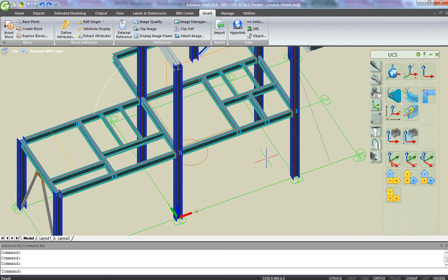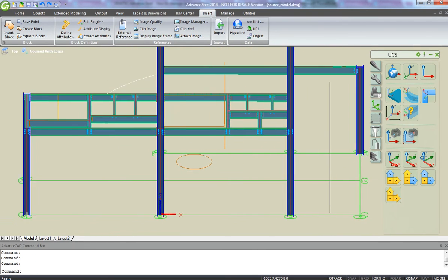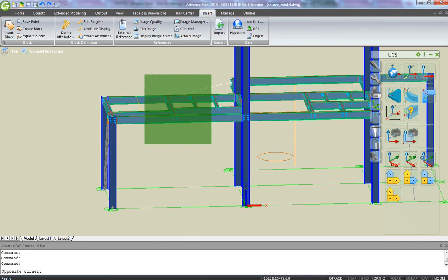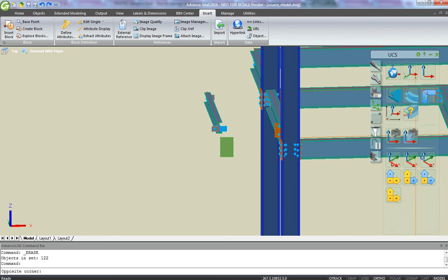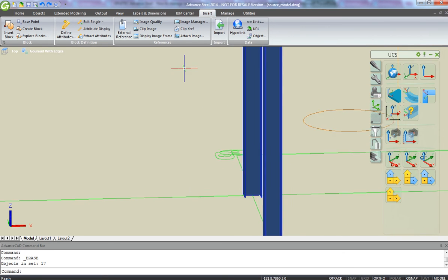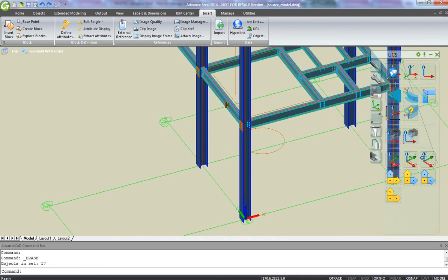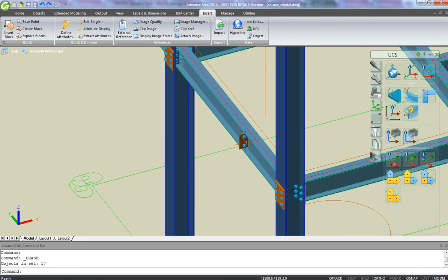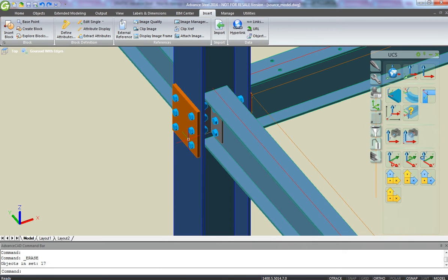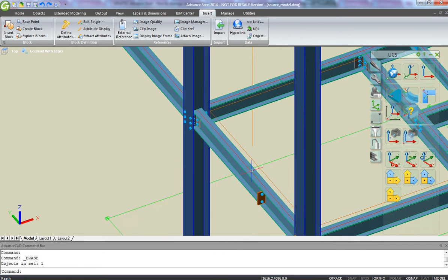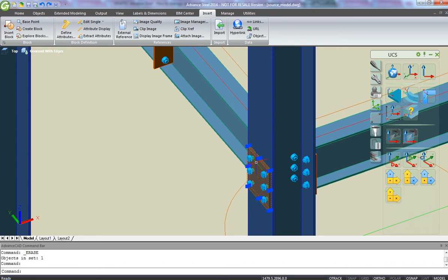Okay, and now of course the next step is to create M2, so the other half. This one is easier because I can delete all these elements in one step. Okay, we can leave the grids here, it doesn't affect. Okay, so in the previous, in M1, you notice that I increased the bolt size. Here we delete this plate, also this plate, and with the bolts we have to do an important setting.